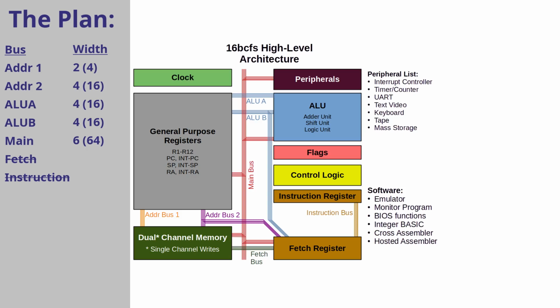The last thing to call out is that I'm intending to be able to swap bytes in my 16-bit registers, and for that I've got a swap bus, which is really a pseudo bus. What it is, is a second entry point out onto the main bus that swaps the bytes. Now, to properly protect that bus, what I really need to do is increase the number of bits of data from 6 to 7 for the main bus. That should give me enough protection to prevent things from stepping on each other.